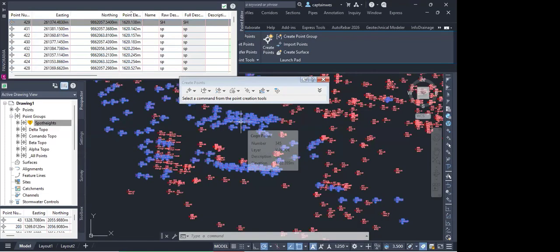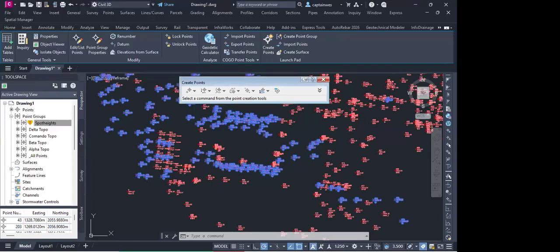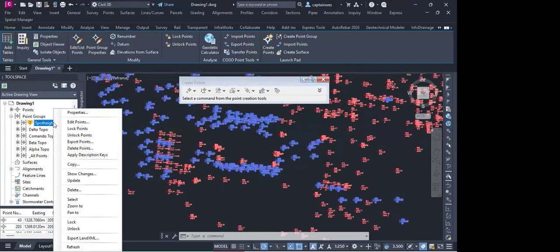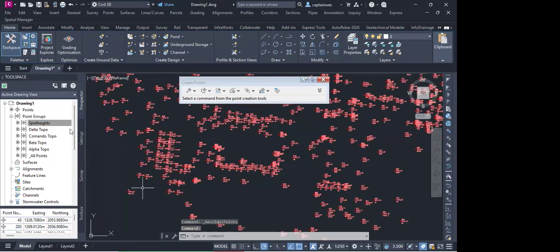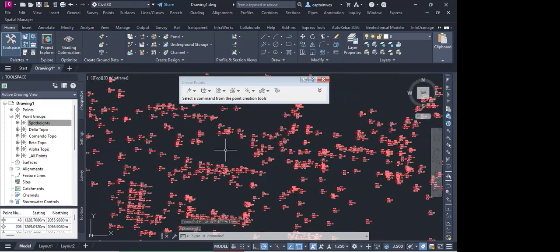This option to edit, just engage it or adopt it when you want to change not more than 10 points. Maybe you want to edit something to do with the description or the elevation. Maybe let's say you did your benchmark. What you recorded is not what is actually there, but someone has the correct value. You can always input the correct value from here. Once you make any change, you update so that the changes you've made are updated.